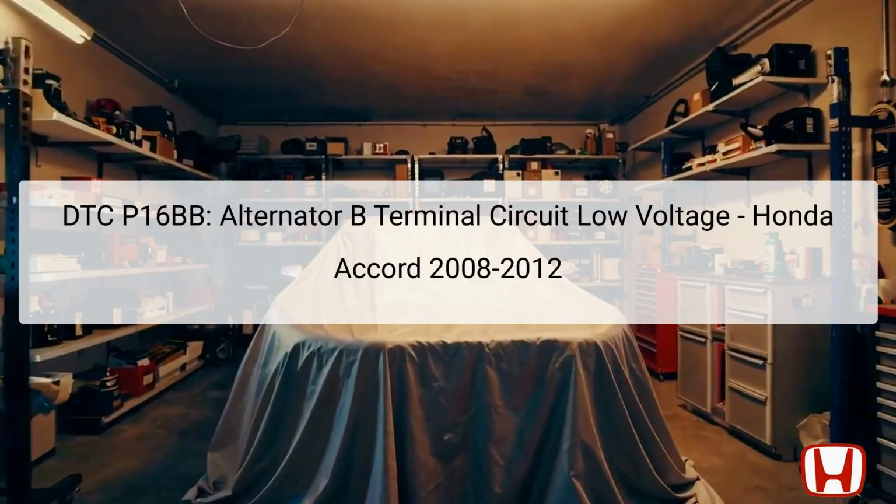The diagnostic trouble code, DTC P16BB, for the Honda Accord models from 2008 to 2012 indicates an issue specifically related to the alternator B terminal circuit exhibiting low voltage. This code highlights concerns in the electrical charging system, where the alternator is not providing sufficient voltage. The alternator is a critical component responsible for generating electrical power to charge the battery and supply power to various electrical systems while the engine runs.